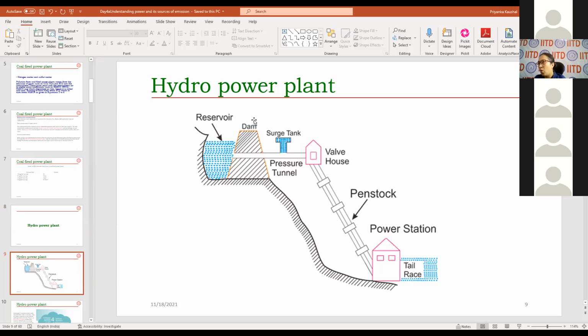So the whole concept of hydropower is in the construction of this dam. This dam could be put to multiple uses. It could be used to control flood, to meet irrigation requirements, so many things. But you need a dam. All the big hydropower plants need a dam. There are run-of-the-river projects wherein we don't construct such a dam. It is the natural gradient that is available. When the water is flowing, we take a slipstream from it, generate the electricity, and make the stream go back and meet the main river, right?